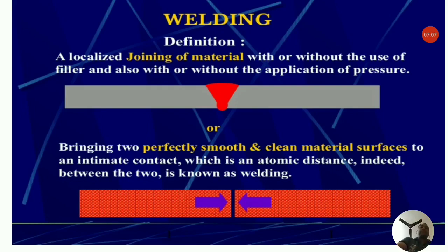Now coming to adhesive bonding, adhesive bonding doesn't disfigure the joining parts, but would generally have less strength than the mechanical fasteners. But adhesive bonding helps in joining awkward shaped parts or thin sheets, which may not lend themselves to mechanical fastening. Similarly, metals and non-metals can also be best joined by adhesive bonding, as in the case of automobile brake shoe linings. Also, the sandwich structure construction for damping structural vibration relies on the damping capability of the adhesive.